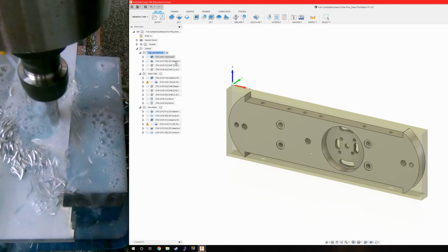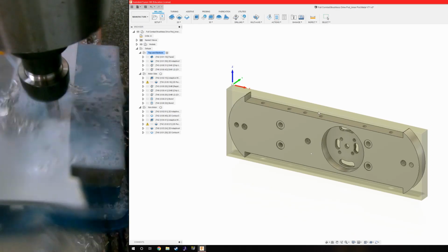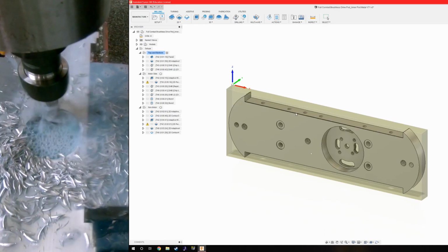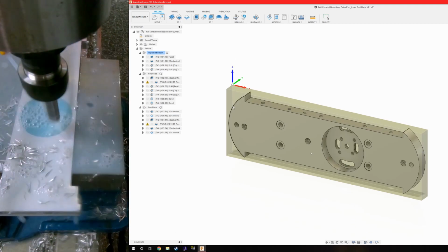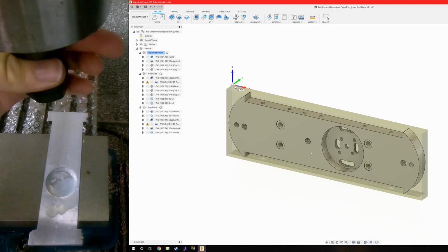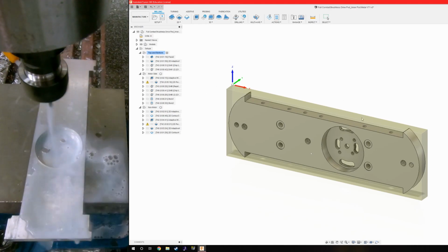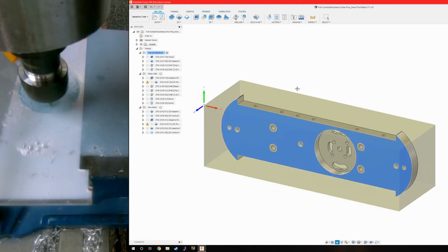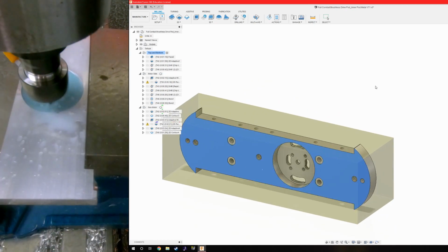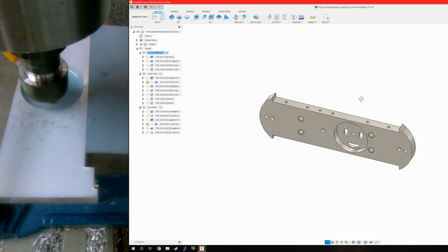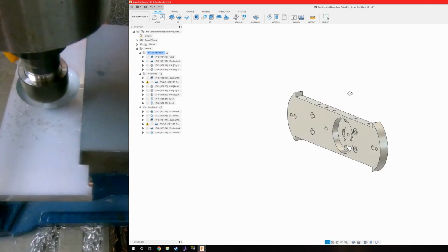In any case, I would stick it in the vise, find the Z, and then do all 3 of them, then flip them over, find the new Z, which was again an 1/8 inch lower than before, or whatever, and then do all of the top and bottom operations again. And then, when I had to do the 2 different faces, the Z's would be the exact same, so I wouldn't have to worry about that because the part was a 1/2 inch tall either way.